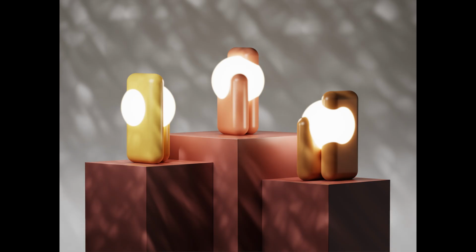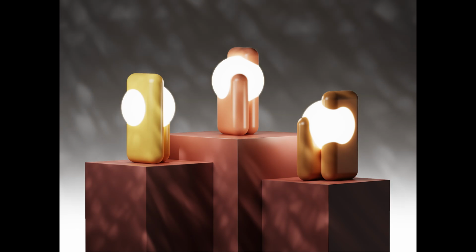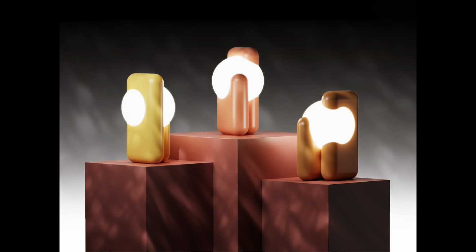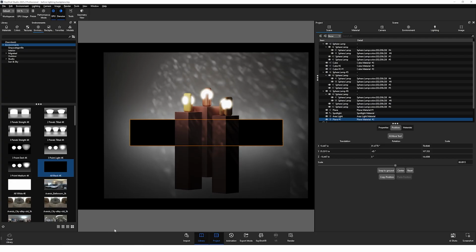Our newly added light at the bottom of our backdrop now adds a nice touch, but how can we elevate this scene further? To direct the scene creatively, the next move is to darken the background's upper section and give the composition more intent. By darkening the upper part of the background, the lamp's bright areas stand out more clearly against the darker backdrop. To darken our backdrop, we'll be manipulating its material.